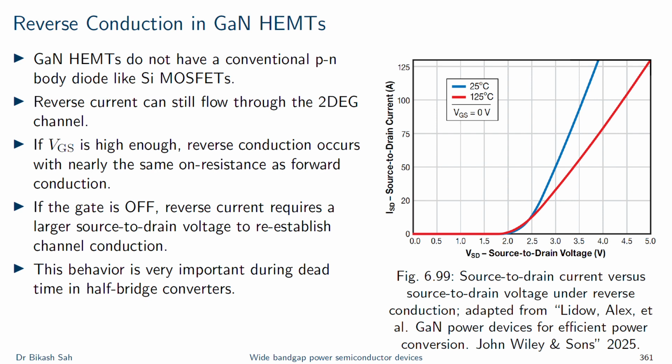Therefore, I would say the dead time optimization in the GaN is super important. It is the central way to achieve high efficiency and avoid unnecessary heating in the system.